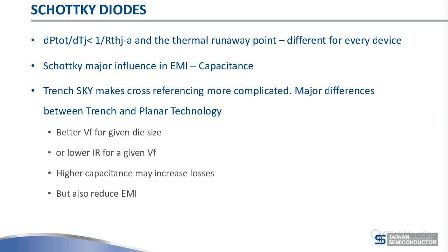However, you need to also look at the trench Schottky as having a higher capacitance, which may increase losses, but may also reduce the EMI. So both products are going to behave completely differently in your circuit, and if you're replacing one with the other, you are really making a new design rather than just cross-referencing parts. So in this case, you really have to watch out and be very careful.